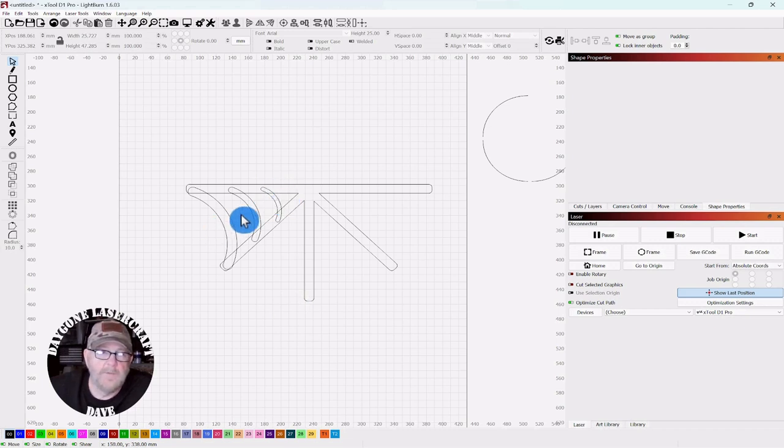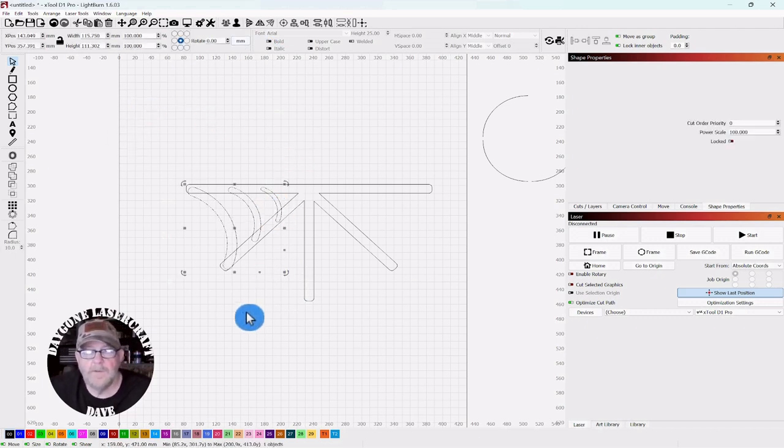Now you can select each one of these one at a time to group them together, which is what we want to do. But I'm going to try to just drag through. If you can drag through without touching anything but those, then you can do that, and then you can go up top and group them together. Because if you drag from the right, you get a green line, and all you have to do is touch the object. If we were doing it from the left and get a red line, you'd have to completely surround the object.